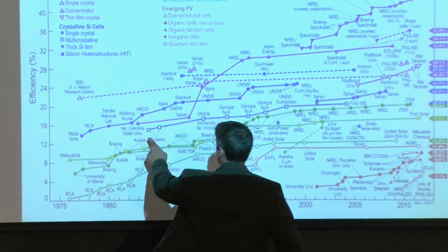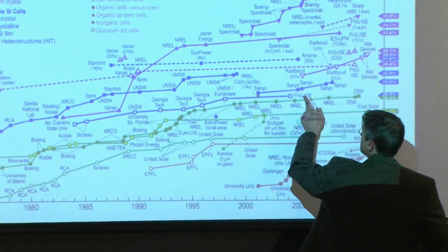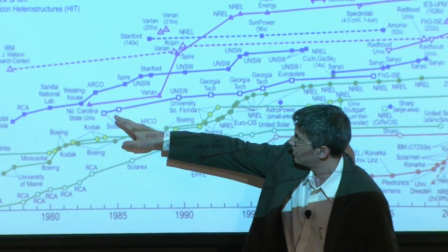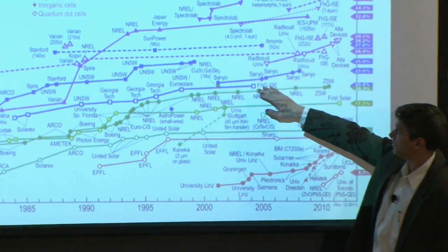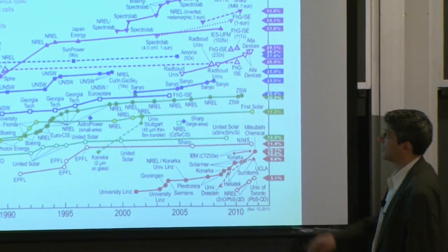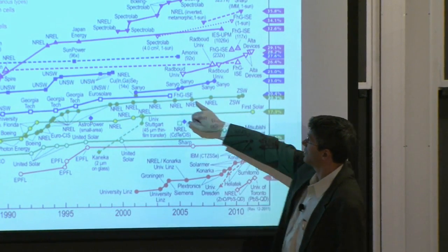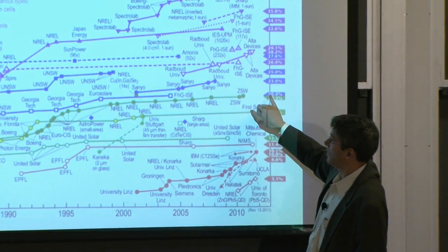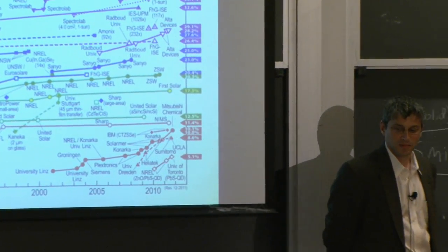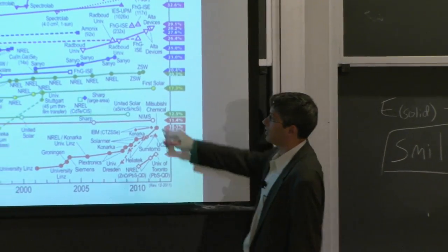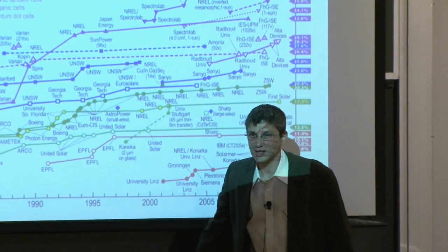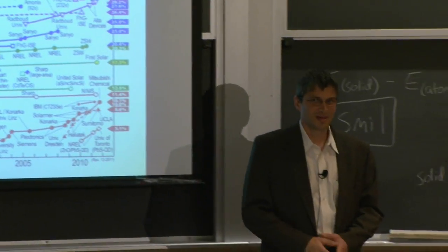So you can find it, right? And that's these squares here. And you can see that silicon has gotten better with time. The efficiency used to be there, and it keeps on getting better. And now, if you want to buy silicon solar cells, you can buy them. I can't get 20% multicrystalline silicon. You can't get that on the market easily, but I can get about 18% cells. Actually, that's not true. Multicrystalline, I can get lower cells.